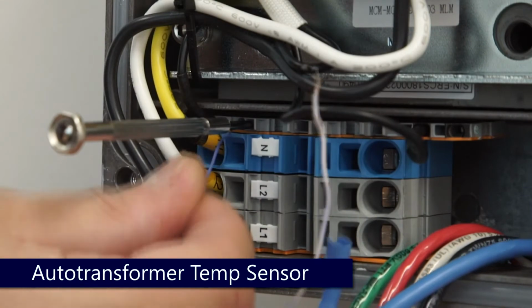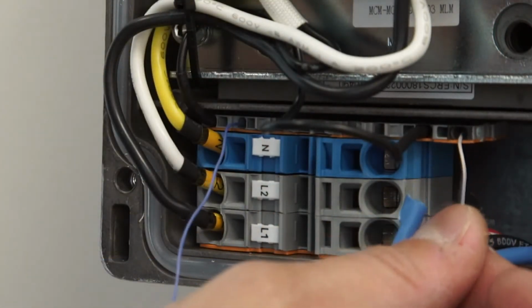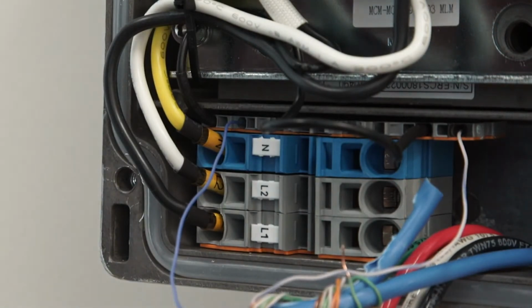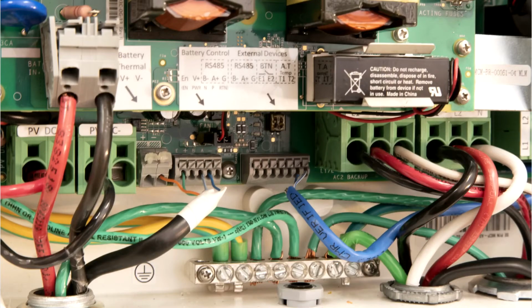Wiring for the auto transformer temperature sensors. The termination block is located above the AC connections inside the auto transformer. Wires land inside the DC disconnect under AT temp 1 and 2.